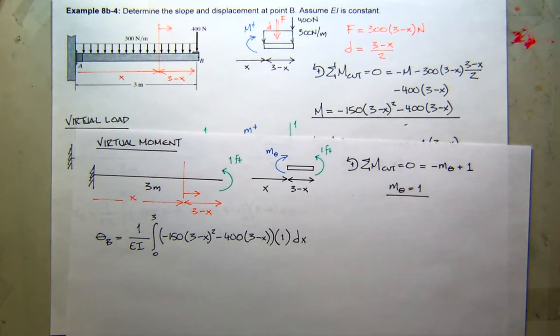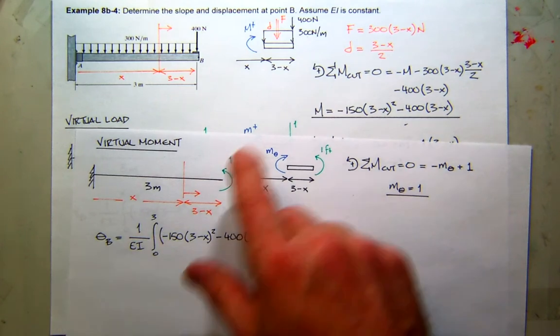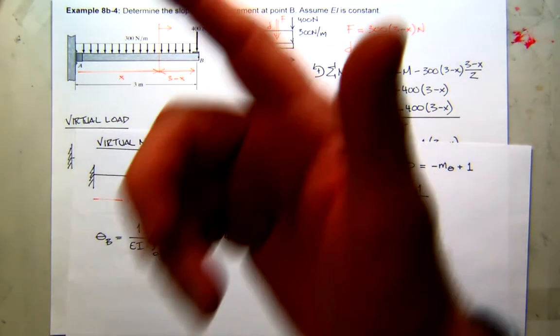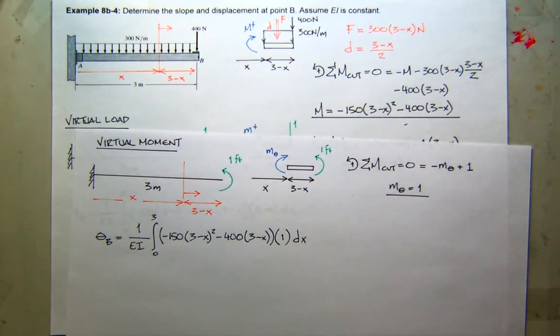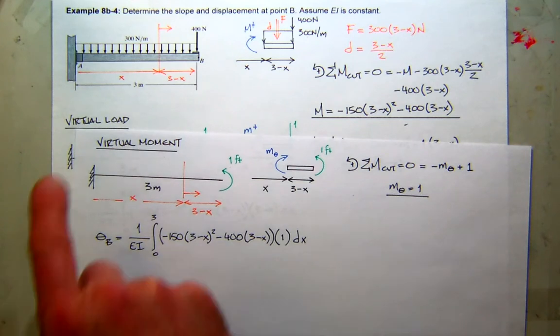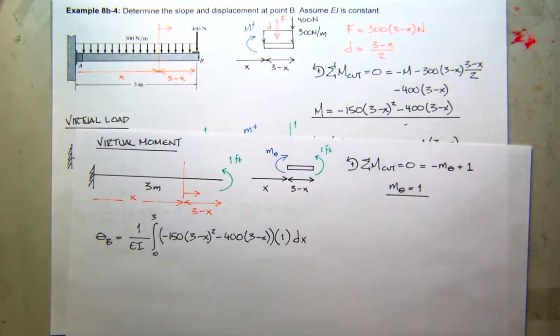And then all I have to do is plug in x equals 3, and I have my displacement. And of course, along the way, you get the slope equation, right? You integrate the moment, you get slope. Integrate the slope, you get displacement. And I just go back to my slope equation and evaluate it at 3, and there's the slope. So I would probably choose direct integration, then virtual work, and conjugate beam dead last. I'd put that one off. This would not be a good conjugate beam problem. Now, if the distributed load was gone, it'd be a great conjugate beam problem.